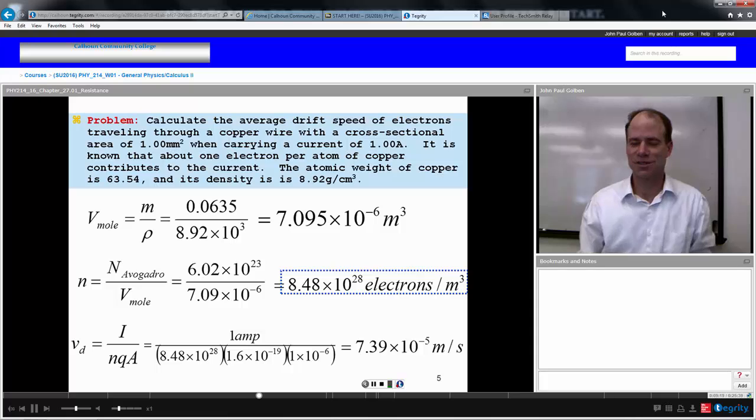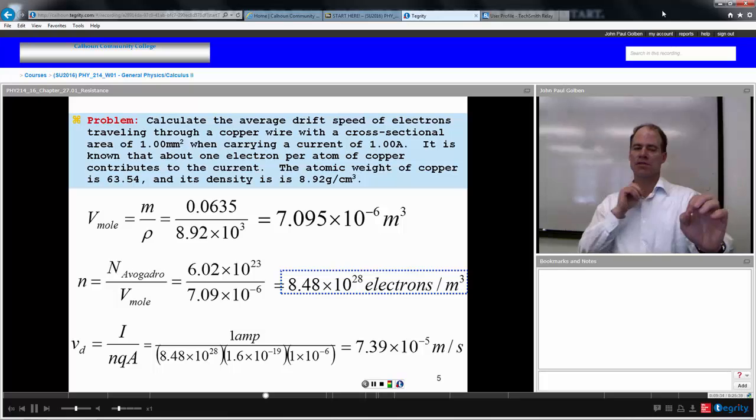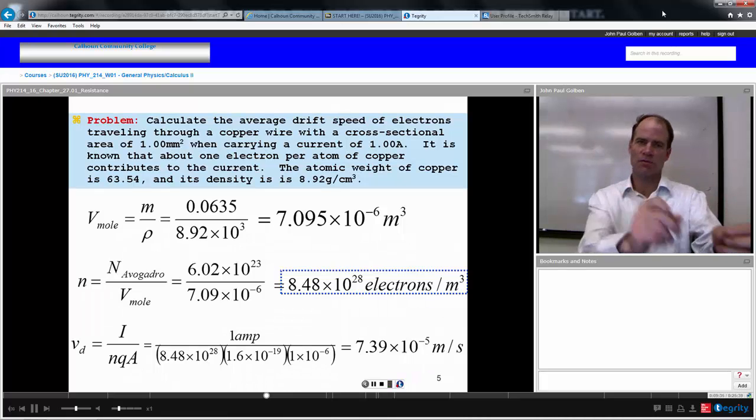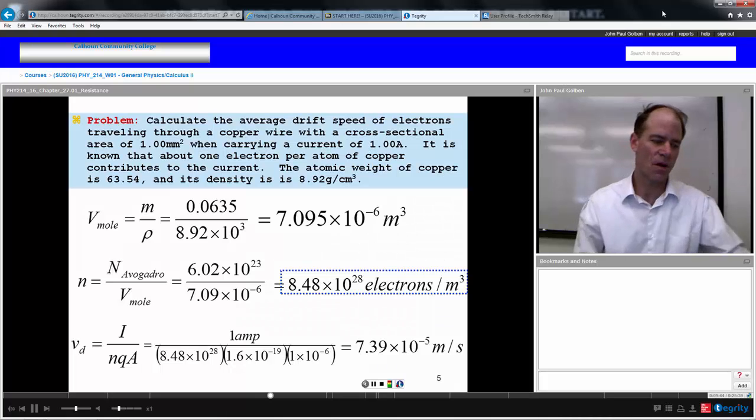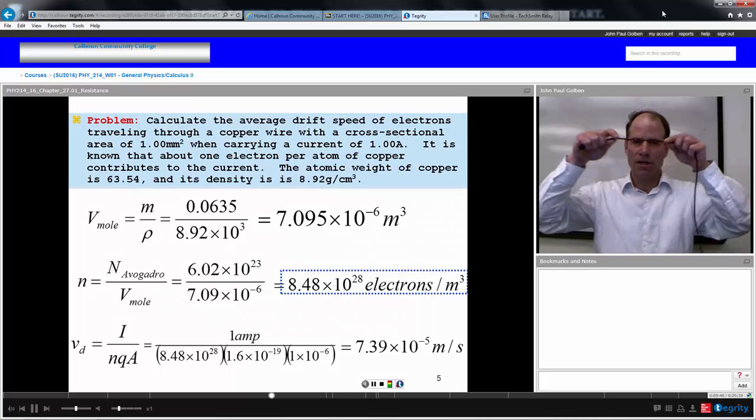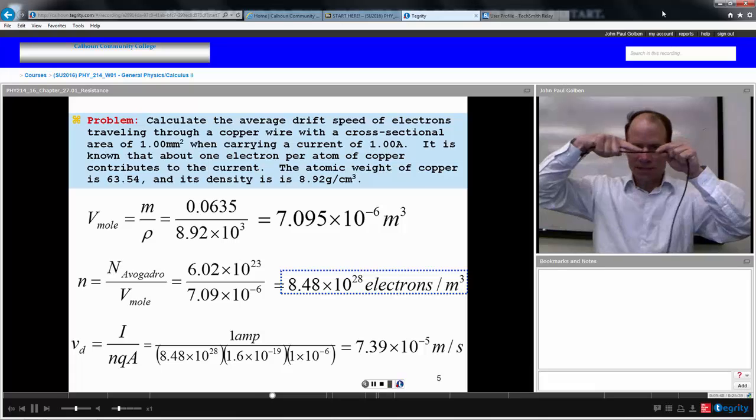The answer to this quiz is yes and no. We have electrons, and they are traveling indeed at this speed. So in this wire of 1 amp, the electrons are actually taking 4 hours to travel 1 meter. The thing is, though, when we're talking about current, we're talking about charge passing a point per time. So all I need to have current is to have charge past that point.